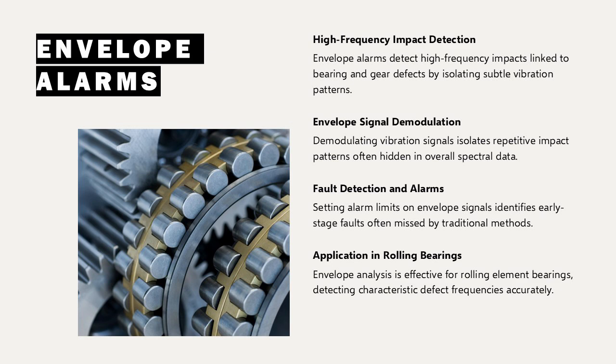Envelope analysis is particularly effective for rolling element bearings, where defects generate characteristic frequencies. Implementing envelope alarms requires specialized software and an understanding of fault frequencies, but the benefits include improved fault detection and reduced risk of unexpected failures.